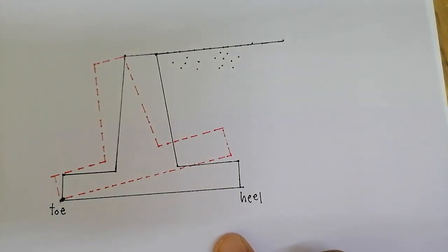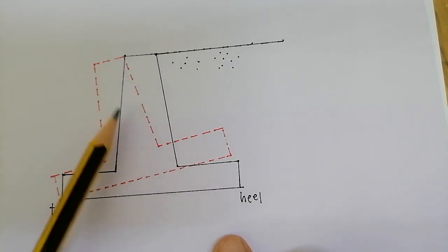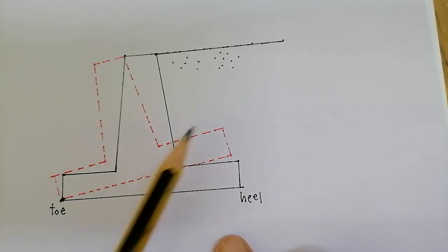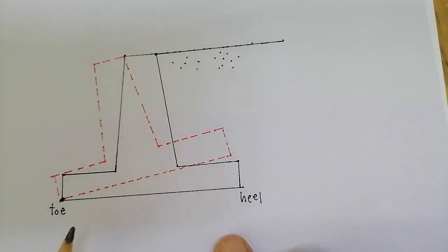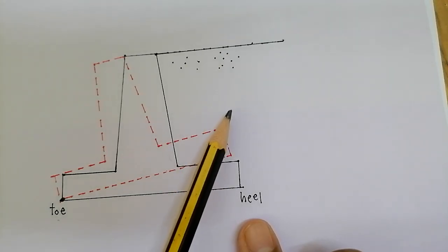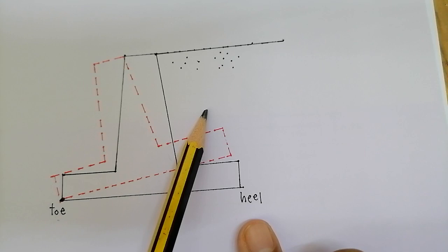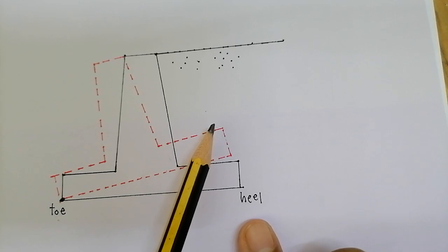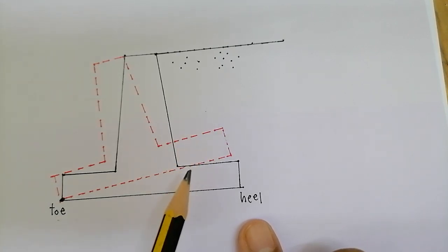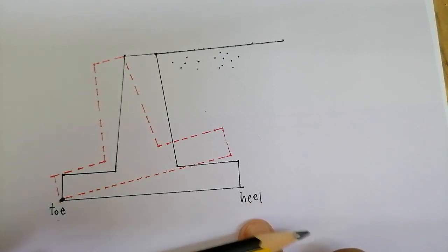I want you to focus on the retaining wall drawn in black pen over here. This is your retaining wall, and back here is the soil, the backfill. For a retaining wall, the front one, we call it toe. The back one, we call it heel. All right. If the force coming from the soil and the pore water behind here is strong enough or big enough, it might cause your retaining wall to overturn